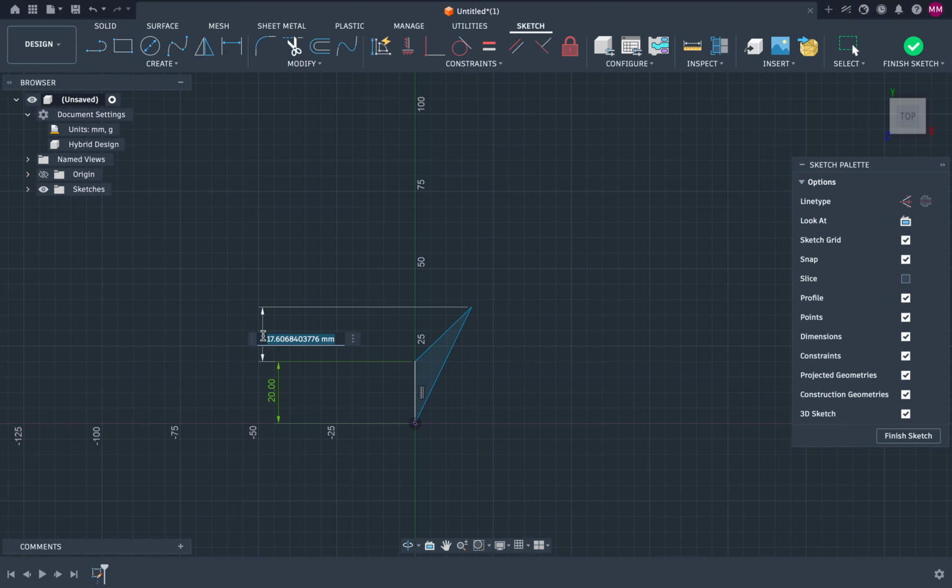to, let's do another 20, and probably we also want to set how far we want it to stick out, and again let's put it around 20, and this actually looks better. Now what we can do next, we don't want this sharp corner, and we can use the fillet. We can use fillet here, which is not actually a fillet, but it's a sketch adjuster, or we can get it right there.